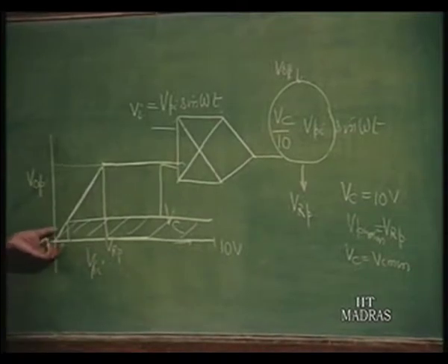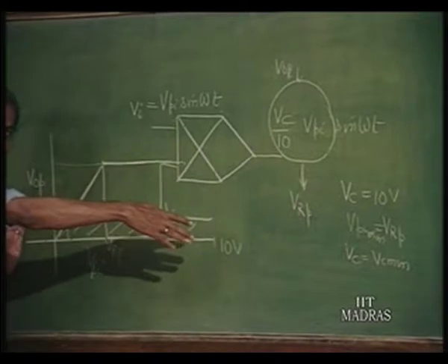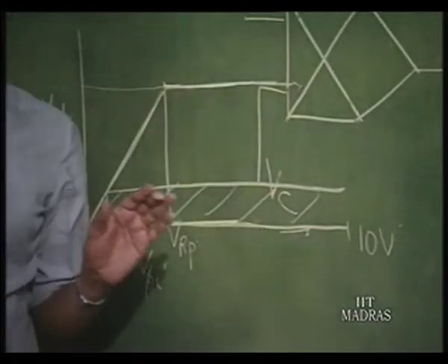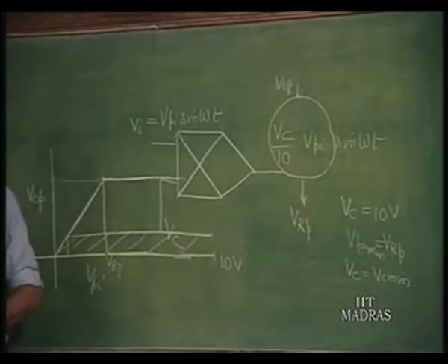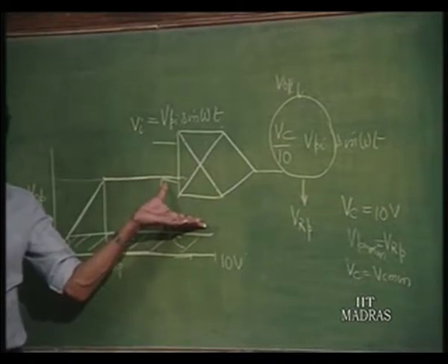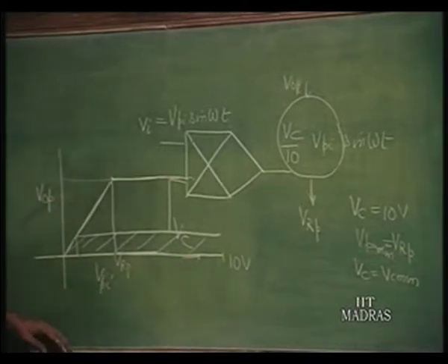If it is to be 0.5 volts, you can see that as I restrict the value of this to lower values, the AGC dynamic range keeps increasing. As I keep on increasing it, let us say I have it at 10 volts, there is no range at all for the AGC system, because my multiplier will stop functioning beyond 10 volts. So, this is how you can arrive at the dynamic range of such systems.